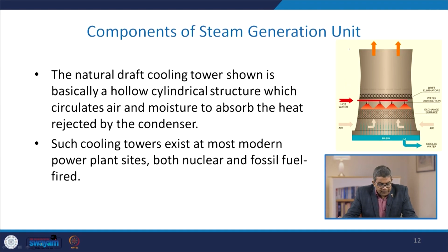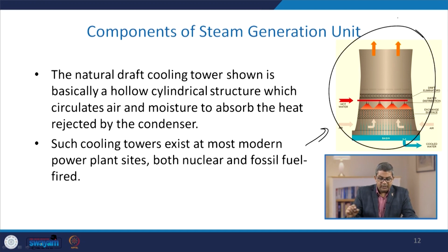Now here, see the cooling tower. The cooling tower is a very important, integral part of any steam generation segment. There may be a natural type or a forced type of cooling tower. The natural draft cooling tower, which is shown here, is basically a hollow cylinder. You see that this is a hollow cylinder which circulates air and moisture to absorb the heat rejected by the